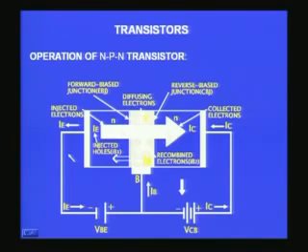So you can immediately see there is a voltage amplification because of the transfer resistance. This is a low resistance region, this is a high resistance region, I am pushing a current through that. For pushing the current I require a very small voltage. Therefore there is an amplification, a mechanical advantage type of thing. With a small voltage you are able to push a large number of electrons, and these electrons are automatically collected by the collector through a high resistance region, and therefore you get a voltage gain, there is a voltage amplification.